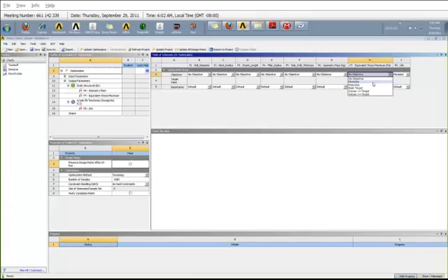And also, definitely, I want to minimize the stresses of the part and also minimize the weight of the part. Since some of these objectives are contradicting, maybe the weight of the part and the equivalent stress contradict each other, because you're saying minimize the weight of the part and at the same time minimize the stress of the part. So it's also good to specify which is important. In this case, I want to give higher importance to my fatigue life, and a little lower importance to my stress and my mass, or the weight of the part.